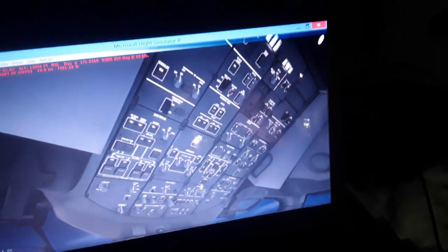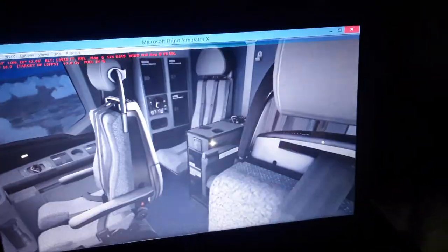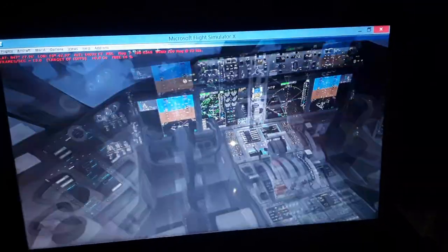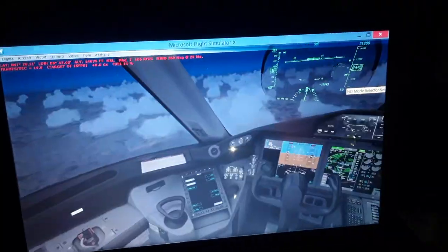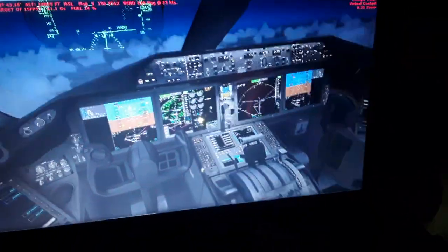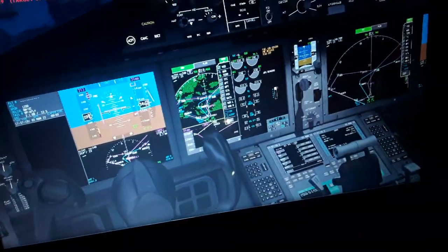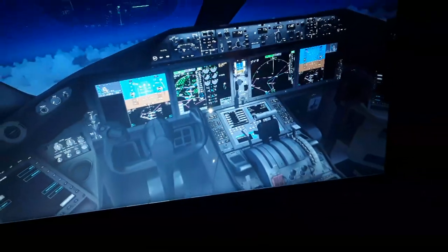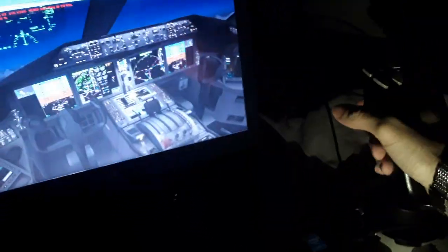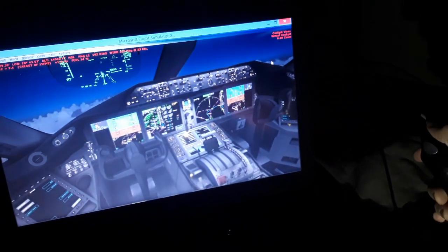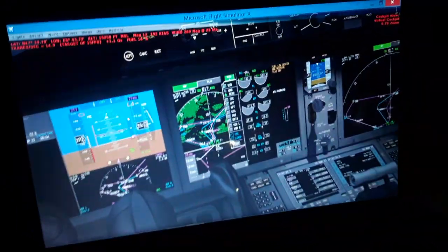So this is a nicer view of the cockpit inside after the takeoff. How it does look like, how bright it is. Perhaps we can retract the flaps more into a higher setting. Maybe retract completely. We'll try and see if it works out. We will accelerate very fast, climb faster maybe, but we need to pitch down the aircraft a little bit to accelerate.